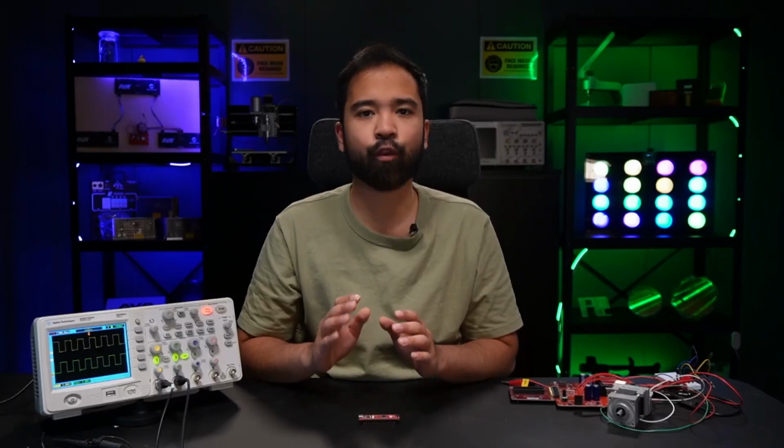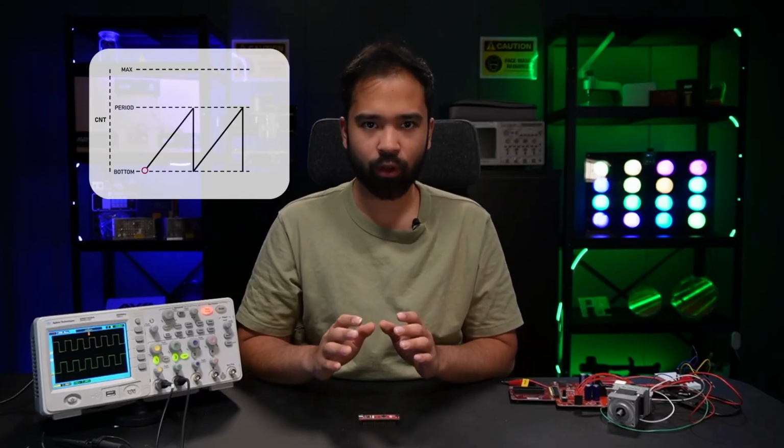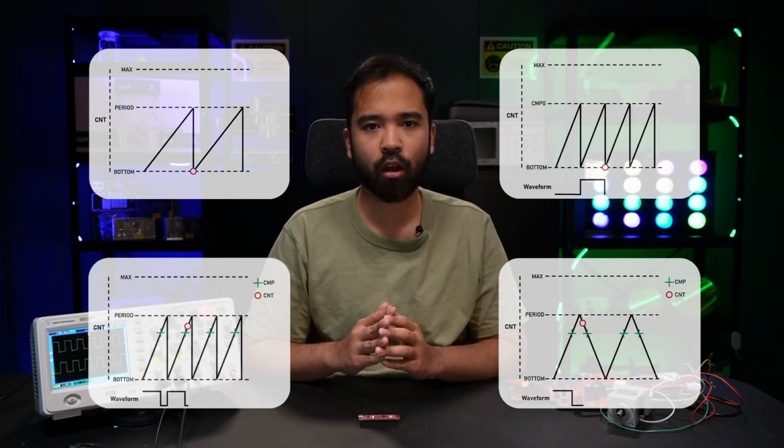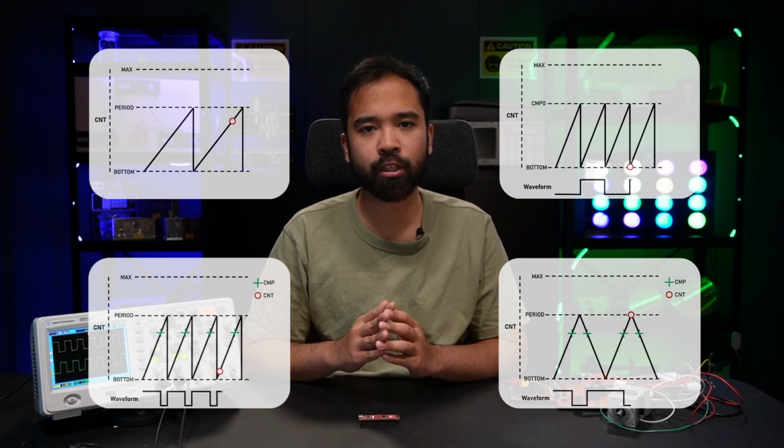The TCE has four main modes of operation: normal mode, frequency generation mode, single slope mode, and dual slope mode. All of these modes can be used with the TCE's high resolution mode. In high resolution mode, we can increase the duty cycle's resolution by 4 or 8 times the normal amount. This mode is perfect for applications that require more precise timing and/or signal generation.